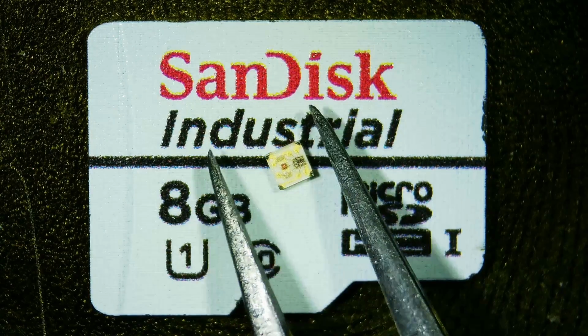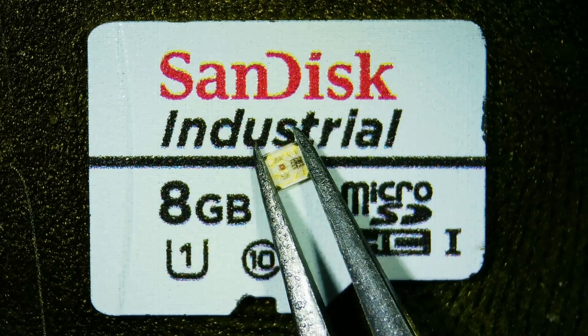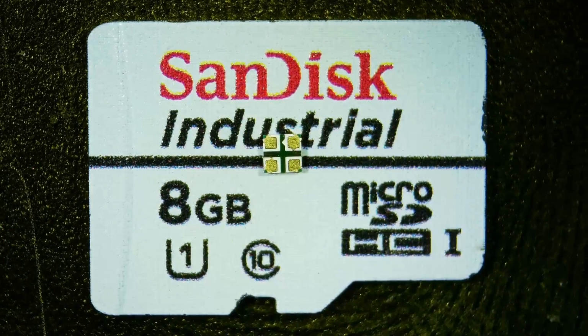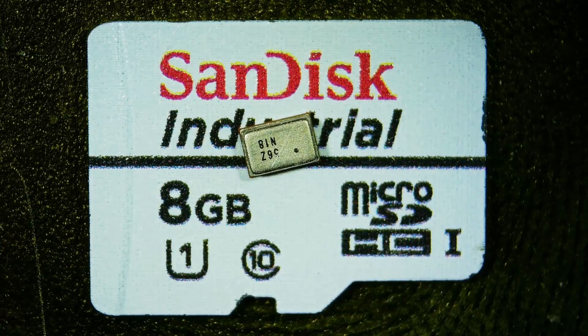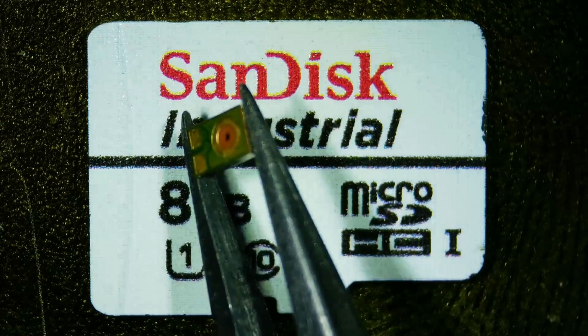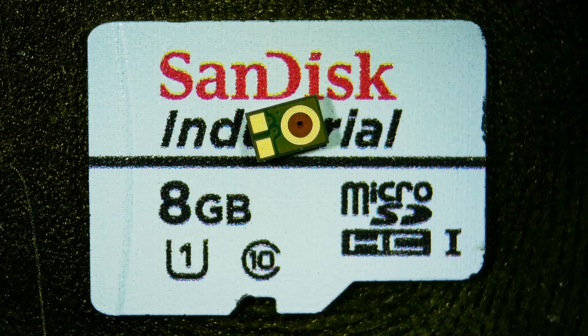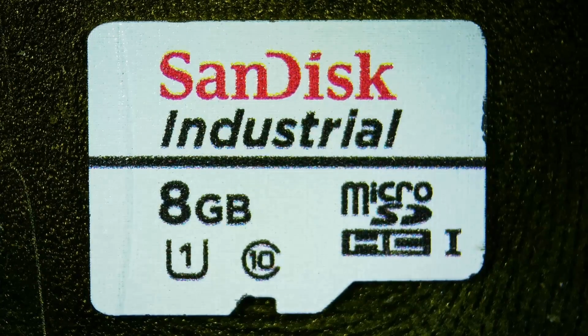So the smaller the board, the cheaper I can buy them, the lower the cost. As mentioned, I chose the SK6805 EC14 LED, which is tiny, thin, and should have no issue going between the tiles. For microphones, I chose the ZTS6156. These are analog output surface mount devices that are slightly smaller than 2x3 millimeters. They have their audio port on the bottom side and have an internal preamplifier, but they do require external amplification to be read directly by the microcontroller's analog to digital converter.